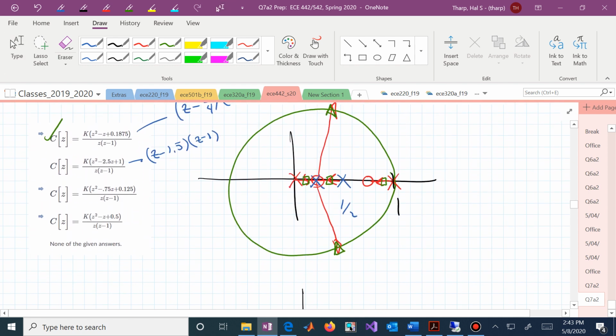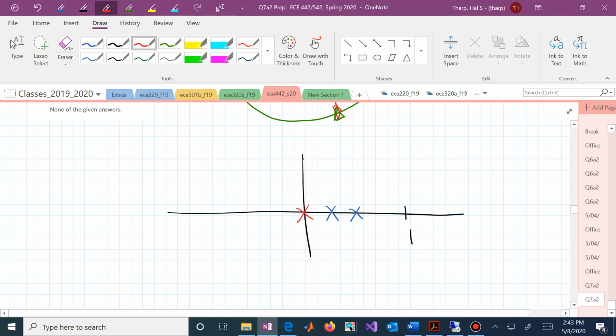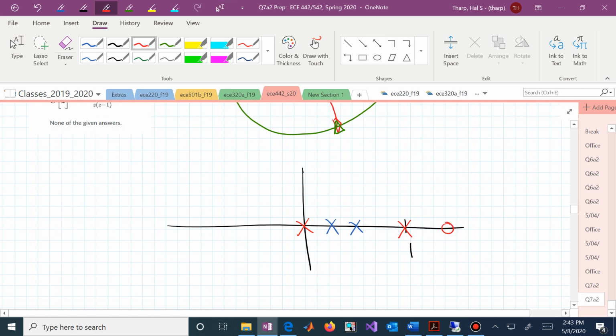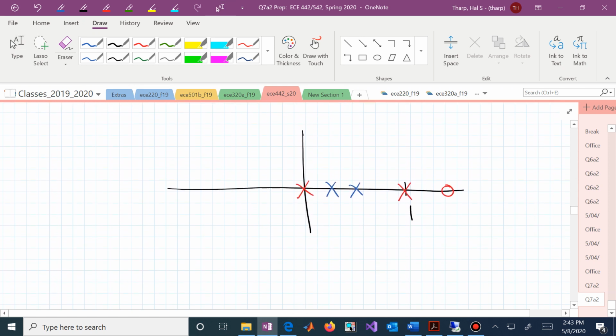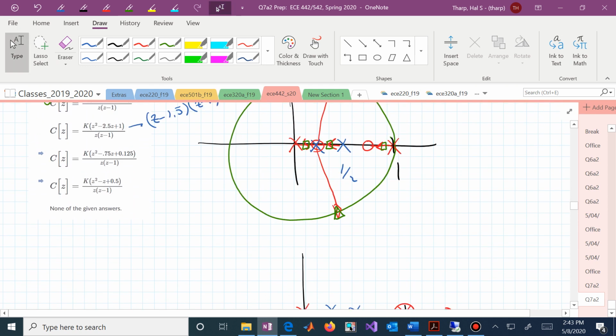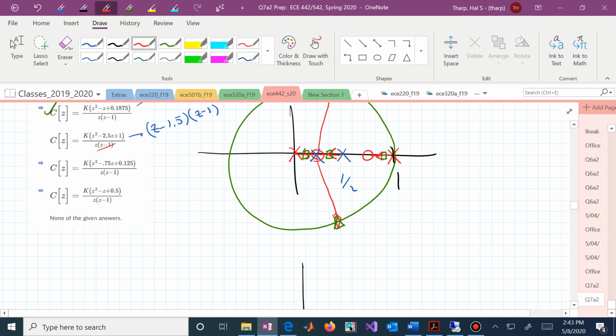We now, for this second transfer function of our controller, are introducing a pole at the origin and a pole at 1, and a 0 at 1.5, and a 0 at 1. And you could sort of say, wait a minute, what are we doing here? We've now introduced this pole zero cancellation, which you could really kind of do, because those are internal to this controller, and you would cancel those prior to even implementing this controller. So that's really okay.